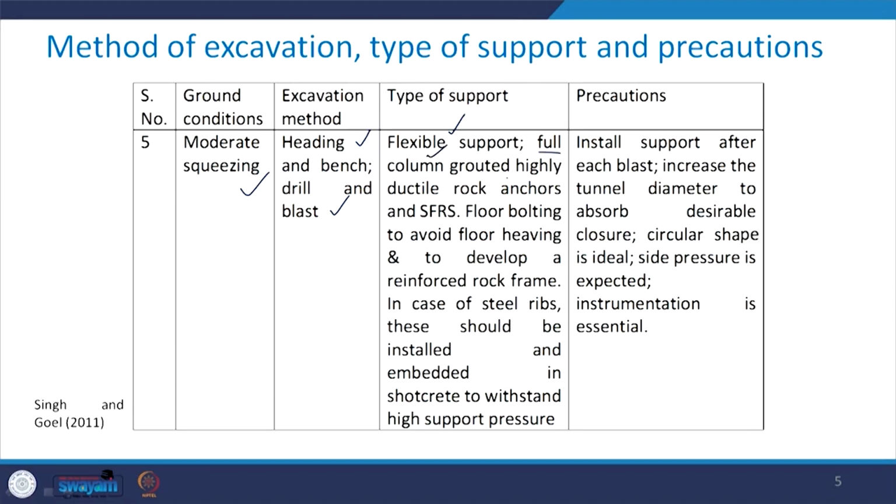Full column grouted highly ductile rock anchors and SFRS. Floor bolting should be provided in order to avoid floor heaving and to develop a reinforced rock frame. In case of steel ribs, these should be installed and embedded in shotcrete to withstand the high support pressure.